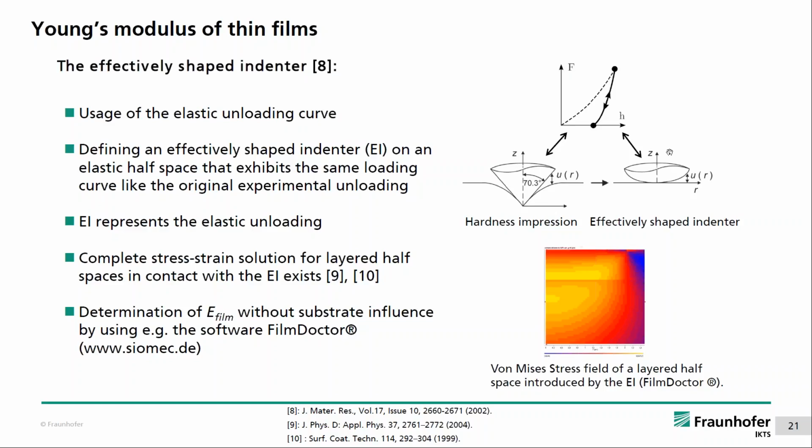And for this mathematical construct exists a complete force displacement solution of layered half spaces and a full stress strain solution. So then you can use this and correct for the substrate influence and get substrate free values also for these elastic plastic indents.